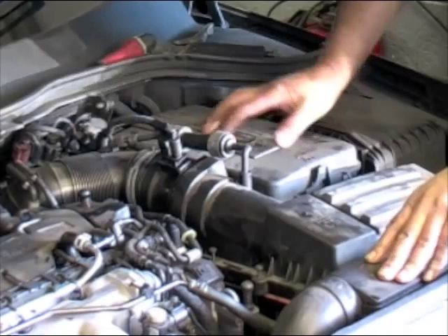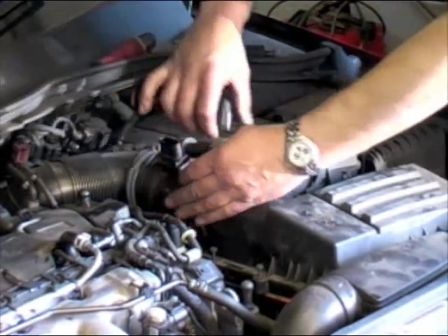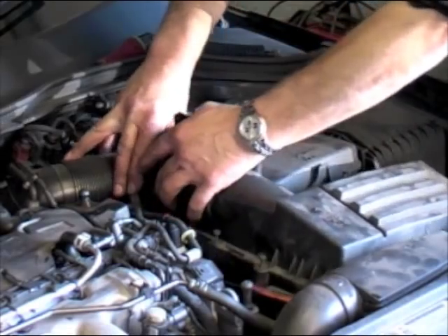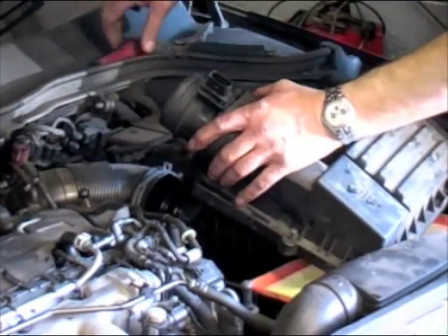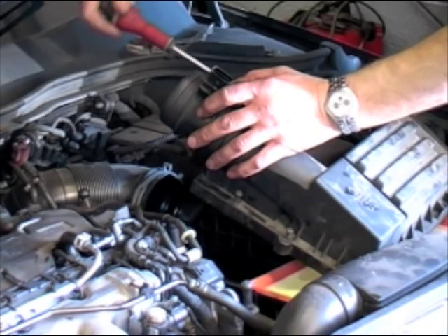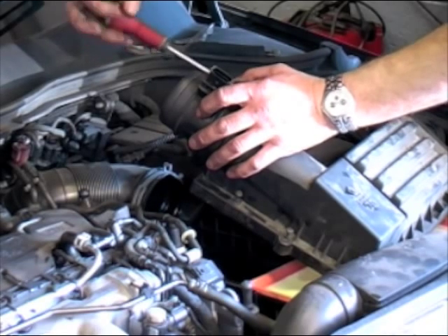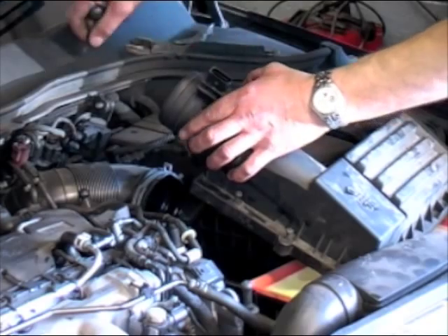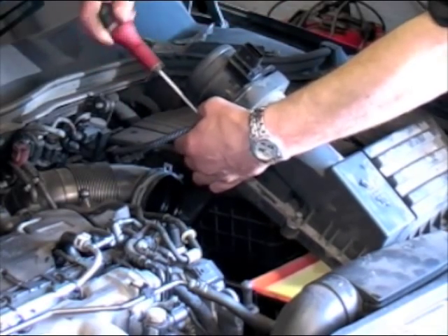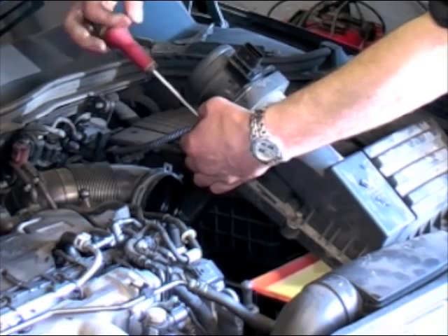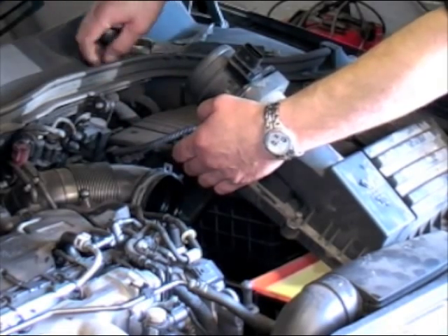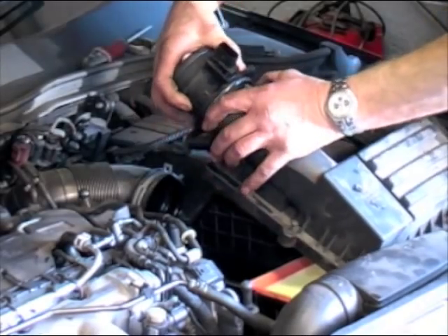The air mass sensor plays a vital role in the control of emission levels in modern diesels, allowing the ECU to monitor and regulate the flow rate of the exhaust gas recirculation valve. The sensor normally consists of a thin heated metal element inside a plastic or metal housing that is positioned in the engine's air intake system between the air filter and the intake manifold. The sensor calculates the mass of air flowing into the engine by measuring the increase in electrical current required to keep the sensor element heated while air flows past it and cools it down.